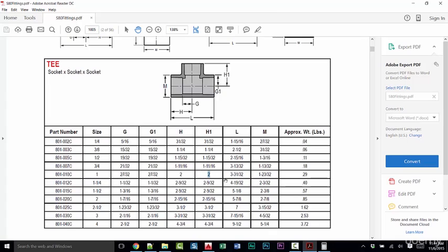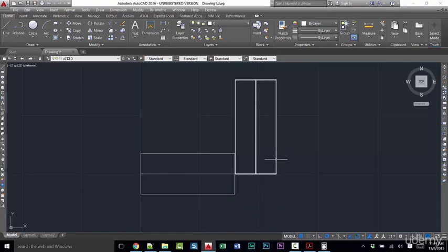That's a nice, easy 2 inches. So that's easy to put in. I'm going to create a construction line here from the extension of this quadrant, and it's going to go up 2 inches. So that's where we need to cut off this tube.